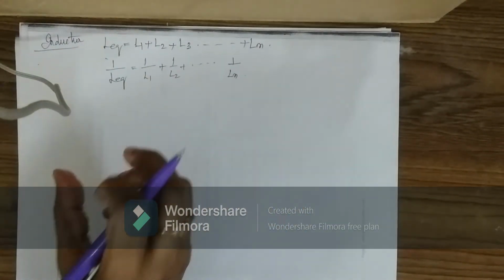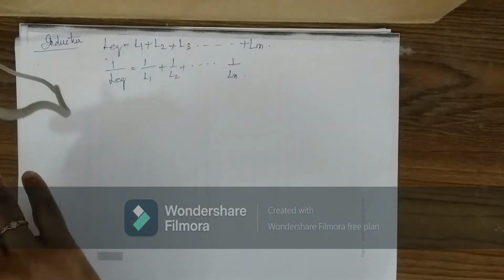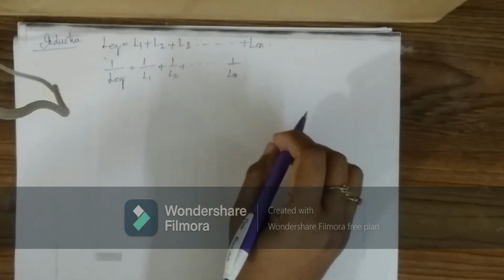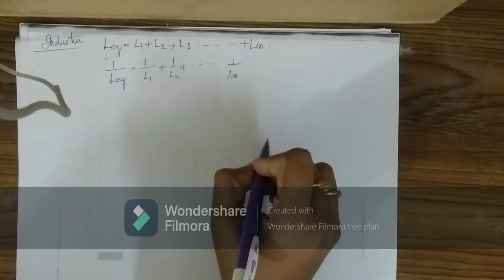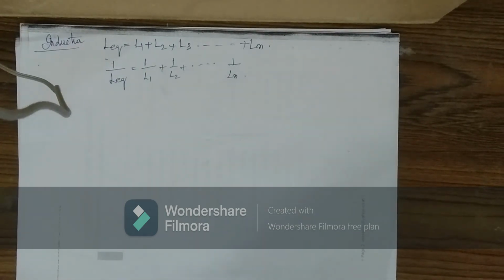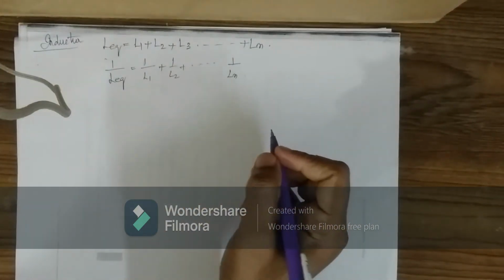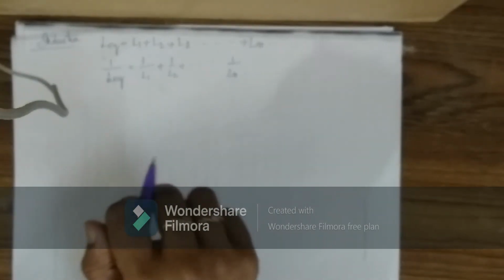When they are placed close together, there will be interacting magnetic fields. For this reason, it is preferable to have a single component. Normally, if there are more inductors connected in series or parallel, they shield the inductors in order to prevent the interaction between the magnetic fields.